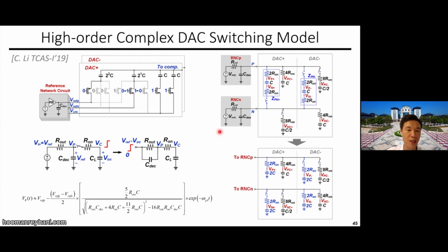In this case, we simplify that. We use this model to give an impulse response, and see how this impulse response goes through this equivalent network and how it reacts at the output. With this output, we can then estimate the error that comes from the non-ideal reference buffer.